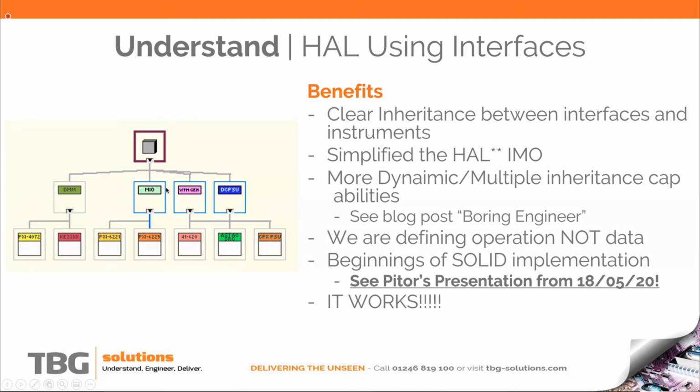So I've got these two, the MIO and the DMM here, really just to show, as you'll see in the code, how we're still leveraging dynamic dispatch. We've got devices that share the same driver layer, both PXI DAQ cards. DMM wise, we've got a Keithley 2200 series, which is a benchtop DMM that is not going to be using NI-DMM. So just to show that we can still use the dynamic dispatch capability in conjunction with interfaces.